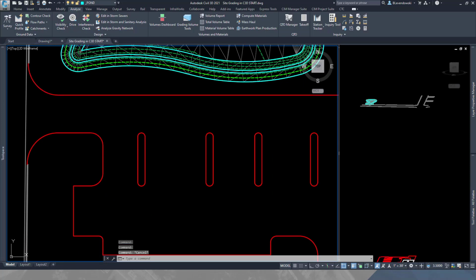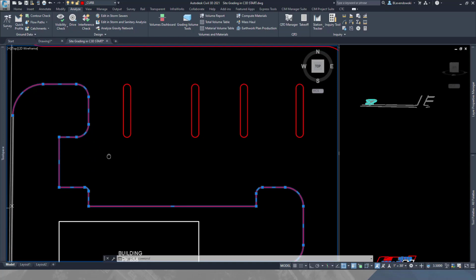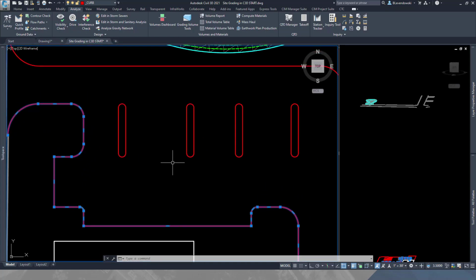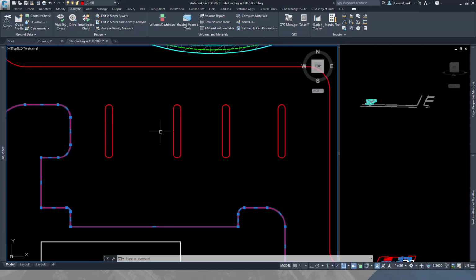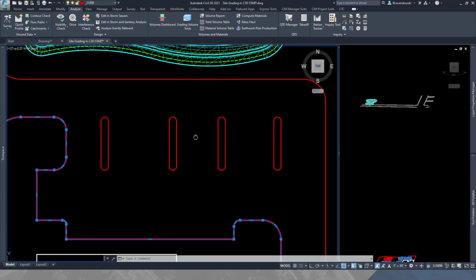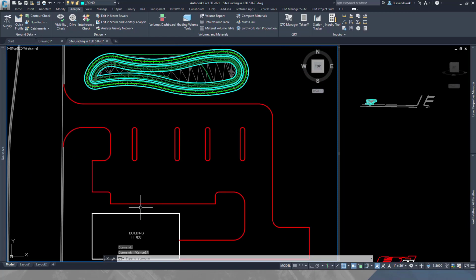With all those curb islands, we have a lot of different vertices that all need different grades or different elevations. We end up with really what can be hundreds of vertices to manage across all of our curb lines. And what we're often after is something like some sheet drainage away from the building, maybe to slope towards the pond, a spillway or something like that.